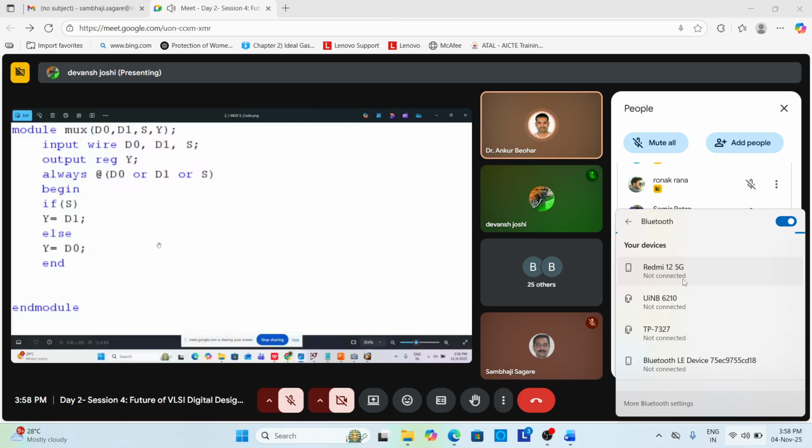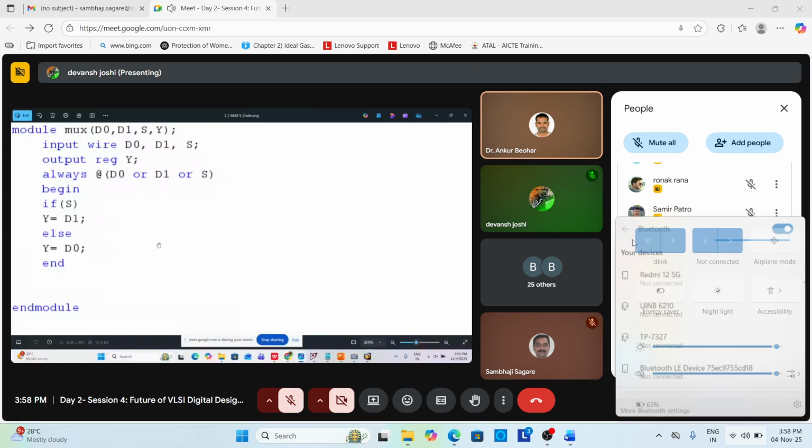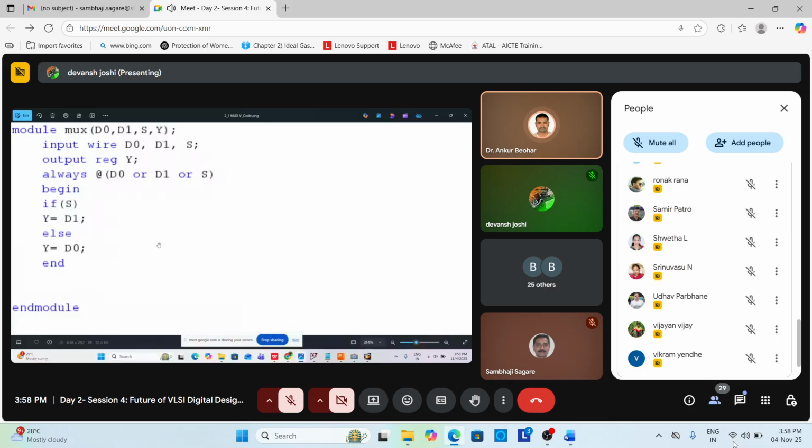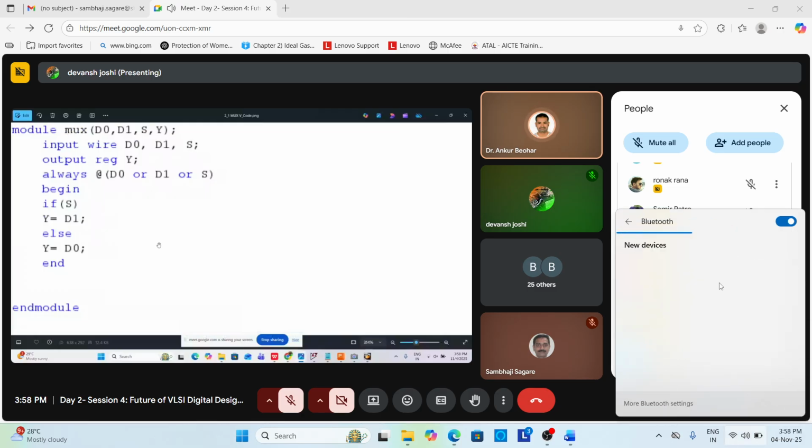So in Verilog here, again, we would like to implement a two-input mux right now in the form of D0, D1, and then we will begin with the output Y. First of all, we know that we have to select one of two inputs; it's the basic principle of the multiplexer to get the output Y depending on a select signal S1.